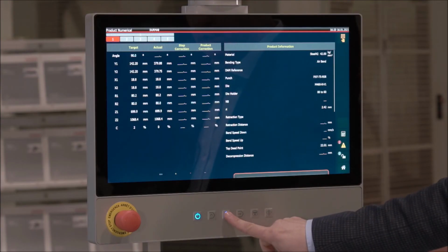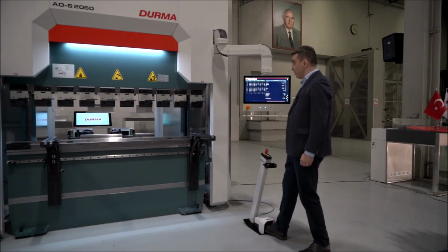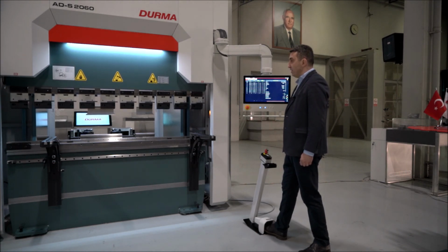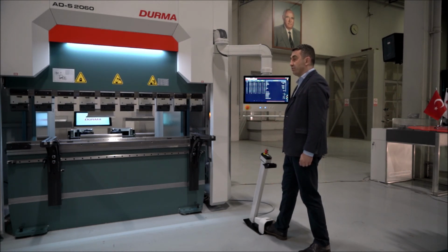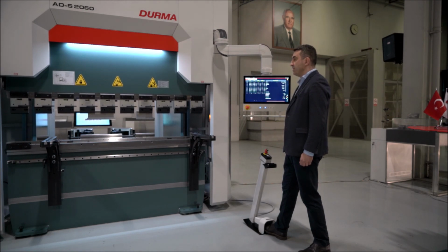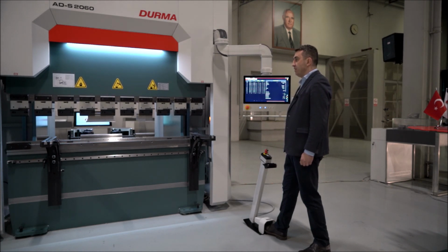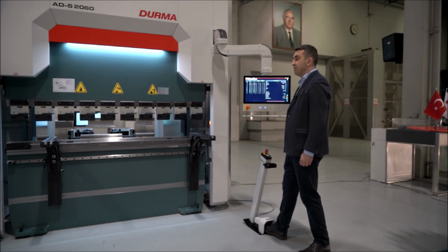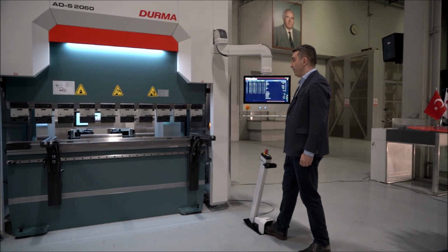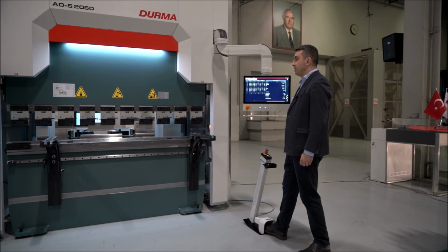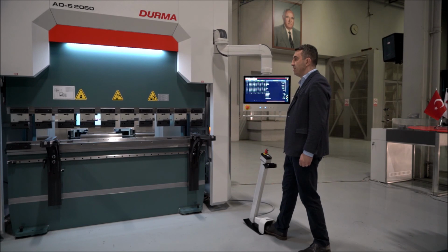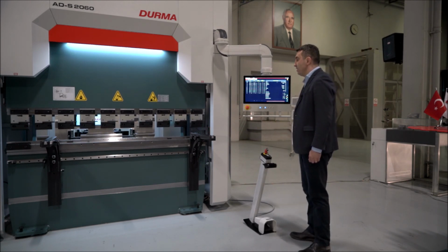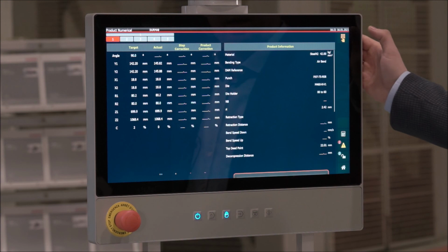After completing our bending, now it is time to turn off the machine. We take our machine to the manual position button, press the full switch, and we have our upper table lowered. The reason we do this is to ensure the raising distance of the upper table, since all axes will take it as reference when we turn the machine on. We lowered the upper table until there was approximately 1 or 2 cm left to the die. Now we can turn off the machine.